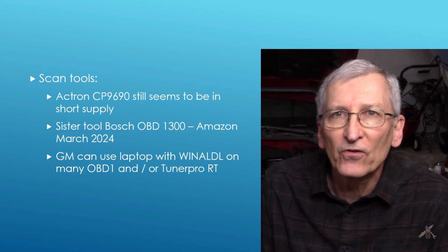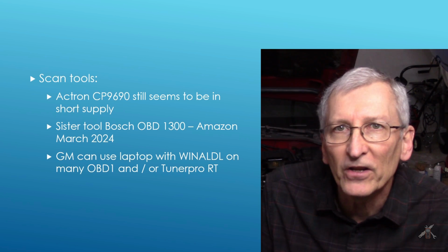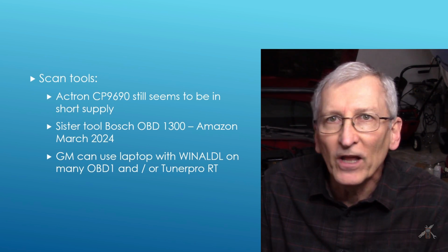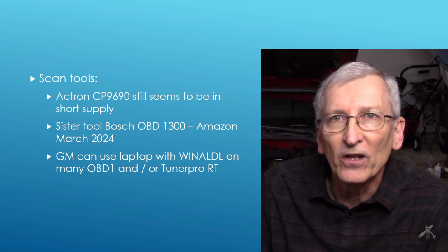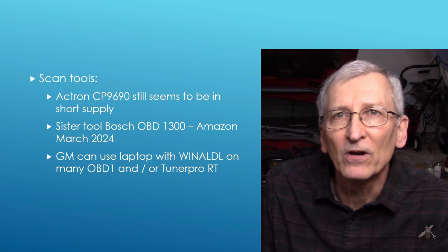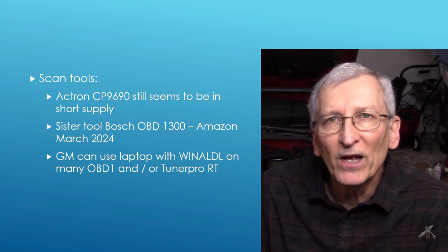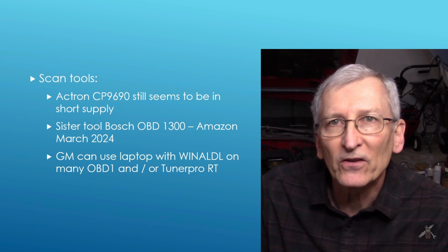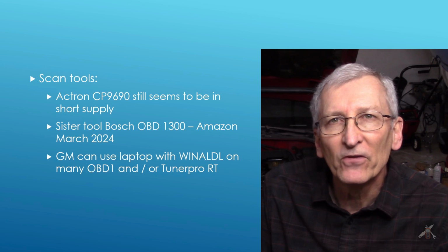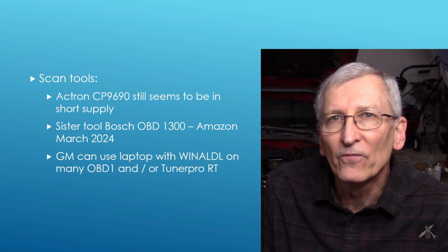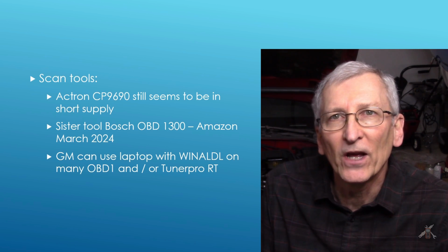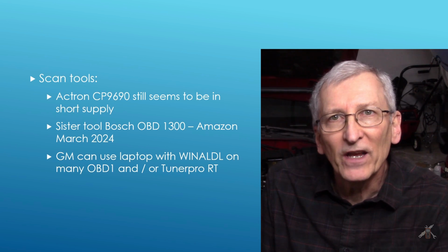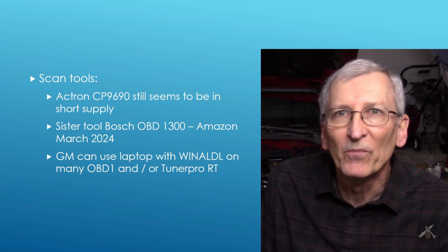I mean, the nice thing about the scan tool is basically you plug it in and you tell it what kind of car you have. It's about a 2-minute thing and you set it up and you go. Whereas the laptop tools are very nice and I use them, but they take a little bit more setup. Somebody asked me a while back, which one do you prefer? And my answer is it depends. When I go out on the road, I always throw the scan tool in the back of the car. If something happens to me while I'm traveling, I can plug in the scan tool in 2 minutes, 3 minutes, and I can figure out what's going on. I don't always carry my laptop with me. Yet if I want to get in and record data, boy, the laptop's really a big help.